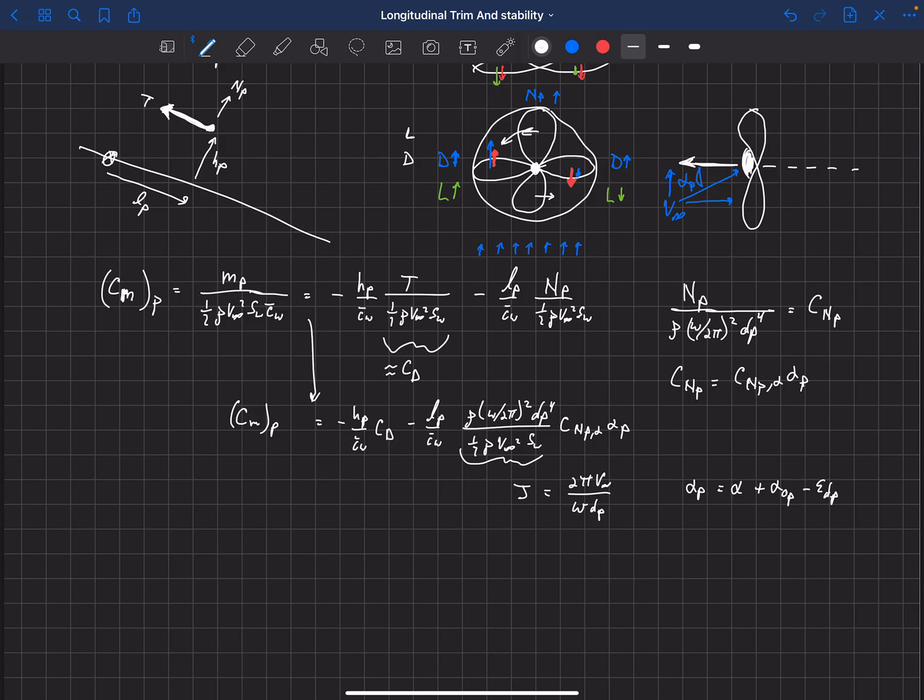That's the downwash at the propeller. What we're trying to do here is include the downwash that the propeller might be seeing due to its presence, due to the fact that it's probably close to a wing. If it's behind the wing, then we're going to get the positive downwash, or it'll be at a lower angle of attack, like we do on the horizontal stabilizer. A lot of times, actually, propellers are up in front of the wing, and so we'll get upwash there.